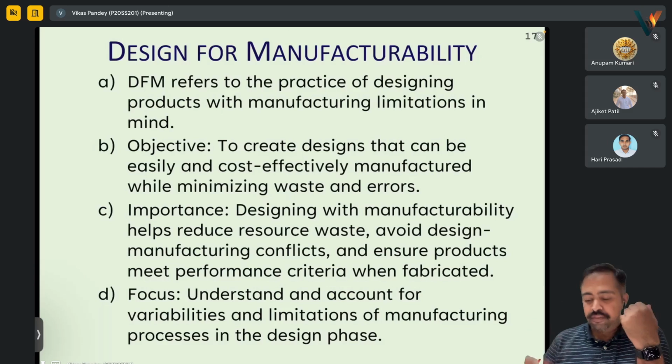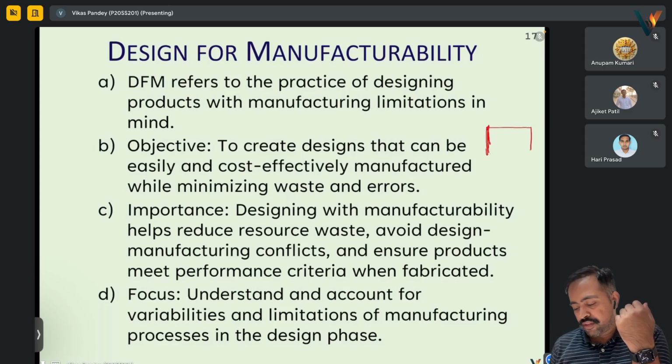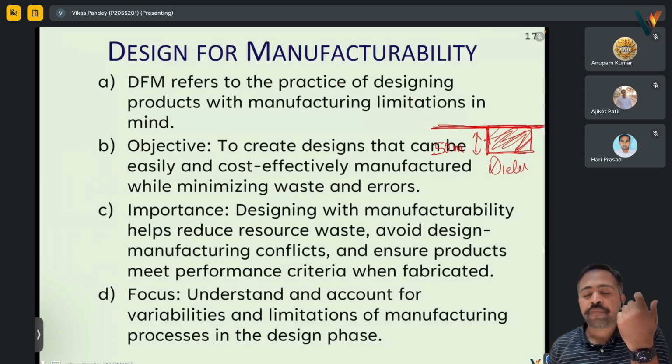Suppose someone says, I will make a dielectric in the gate area, say this will be 50 nanometer, and I will create metal electrodes over it, or say another dielectric, say HfO2, over it, and this overhang will be say 200 nanometer.